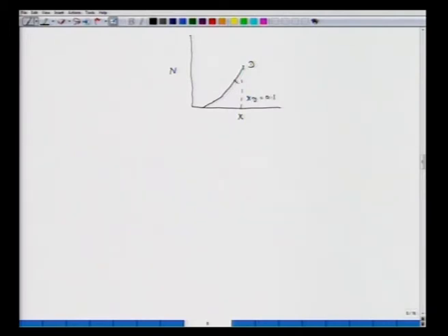This is the non-linear part of the drying curve, the last stage. Corresponding to this D, we have the rate calculated as 0.15, and we have been asked to calculate how long it will take for the moisture content to decrease from 0.1 to X2, which is 0.066.